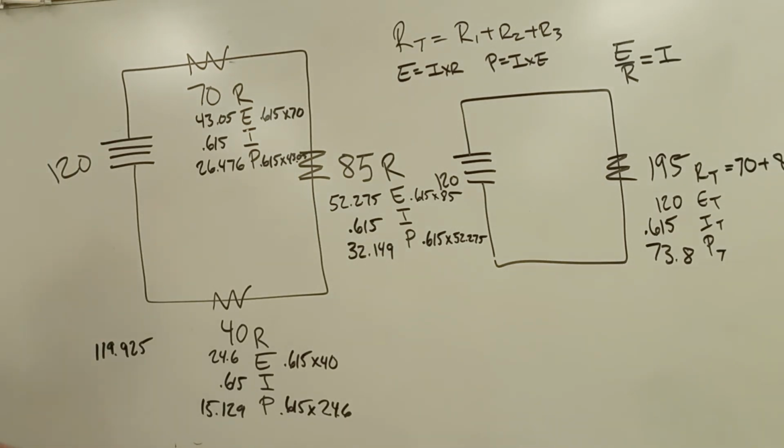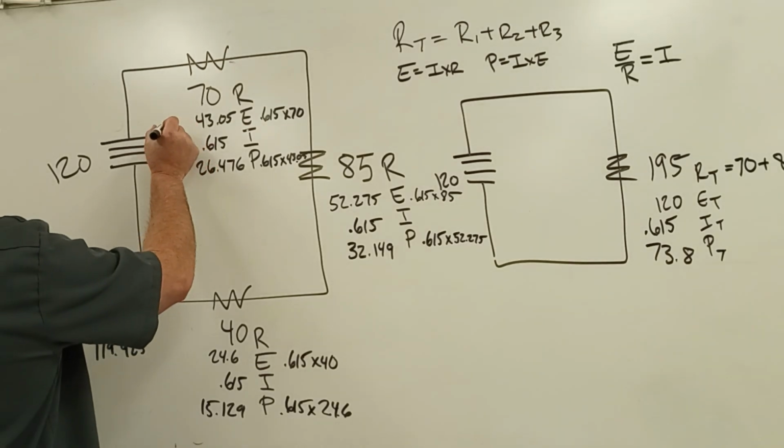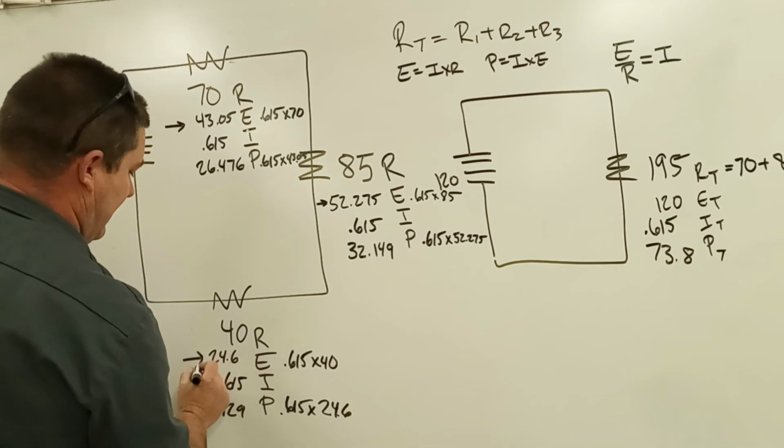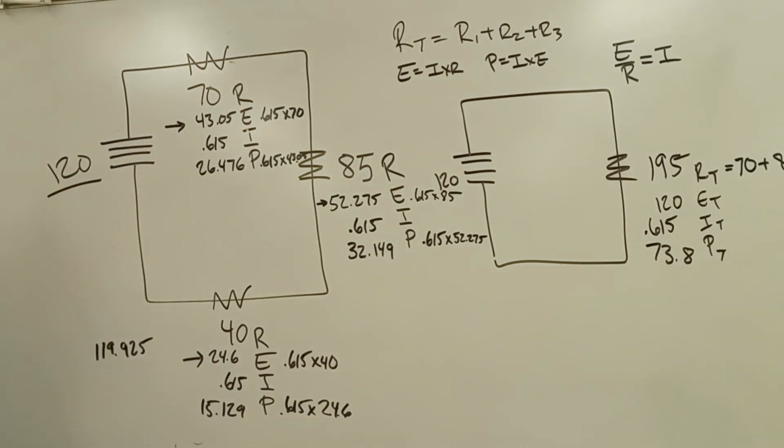What were the numbers that you added together? I'm sorry. All of the voltages. Okay. So you add all of your voltages, and then you check it to what your source is going to be. If you added it up and you ended up with 95 volts, then that should be your indicator. Hey, there's something wrong. Where did I make a mistake? And then you could work your way back through it. But if you're adding them up and you're off by 75 thousandths of 1 volt out of 120 as a percentage, that's pretty accurate.